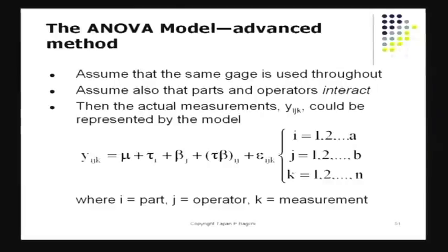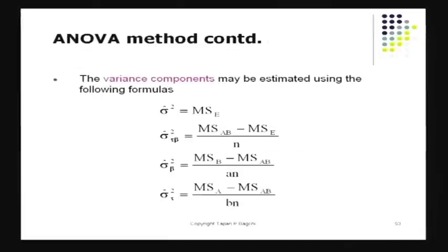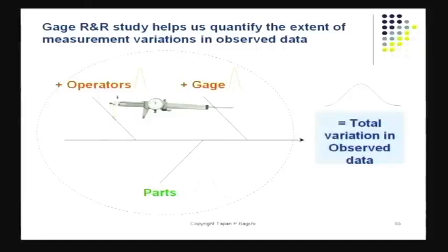And of course, there are fancy methods called ANOVA. Those can also be applied, and they can also be used to do measurement system analysis. The ultimate idea, of course, is you've got to make sure that the measurement system, whatever gauges you are using plus the procedures they are using, does not contribute much. And what you observe is exactly what the true variation is. So therefore, you can rely on the data that you produce, because your decisions have to be data driven.